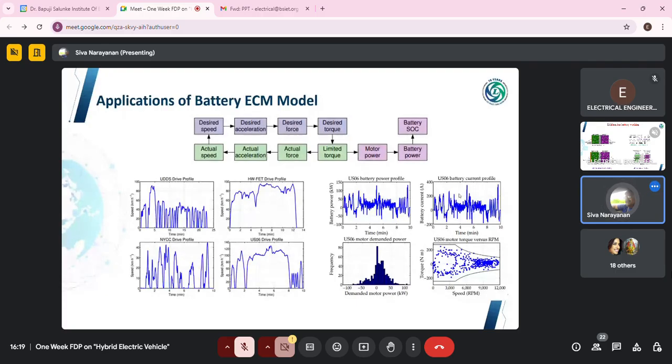From this torque they find the required motor power, and from the required motor power the required battery power is calculated, and here comes our battery pack. From this we will be able to calculate whether our motor power requirement will be achieved by our battery power, and from that battery power, at last we need to verify whether our battery has that particular SOC to achieve this. Generally, vehicle manufacturers fix the battery SOC range. It is between 50 to 75 or 75 to 100.